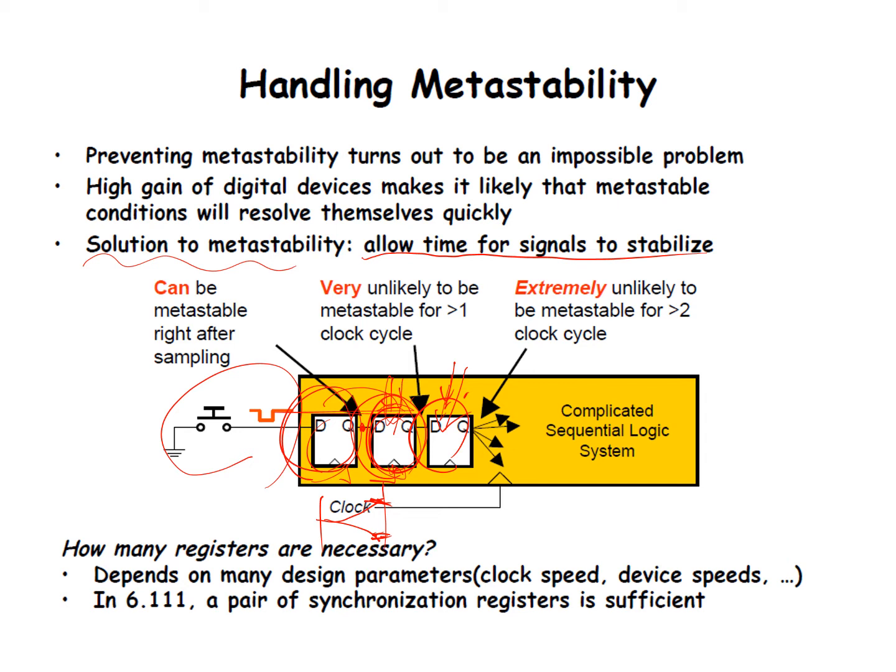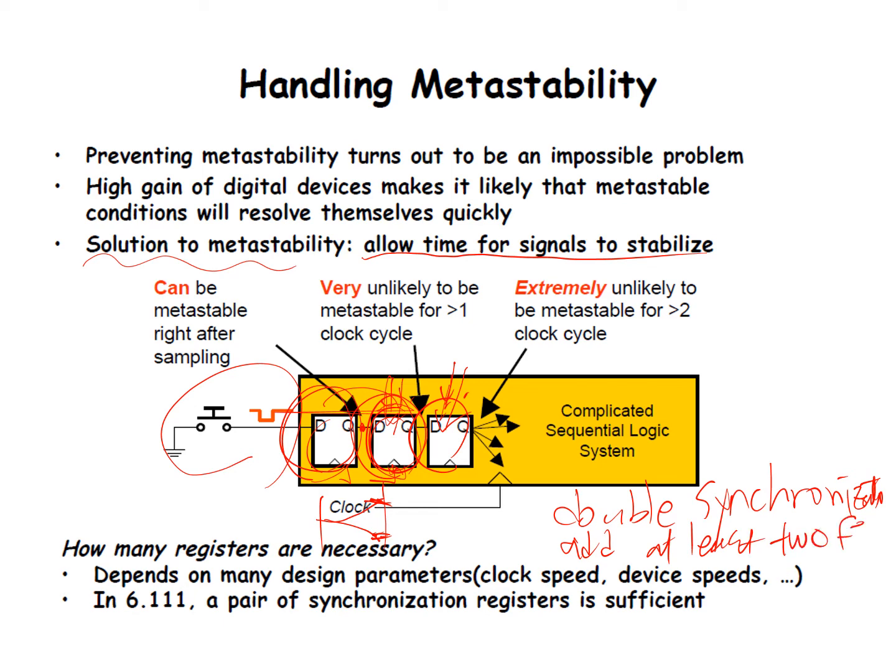Most common practice is double synchronization. So we add at least 2 flip-flops in the path. So double synchronization: add at least 2 flip-flops on the asynchronous interface. Okay.